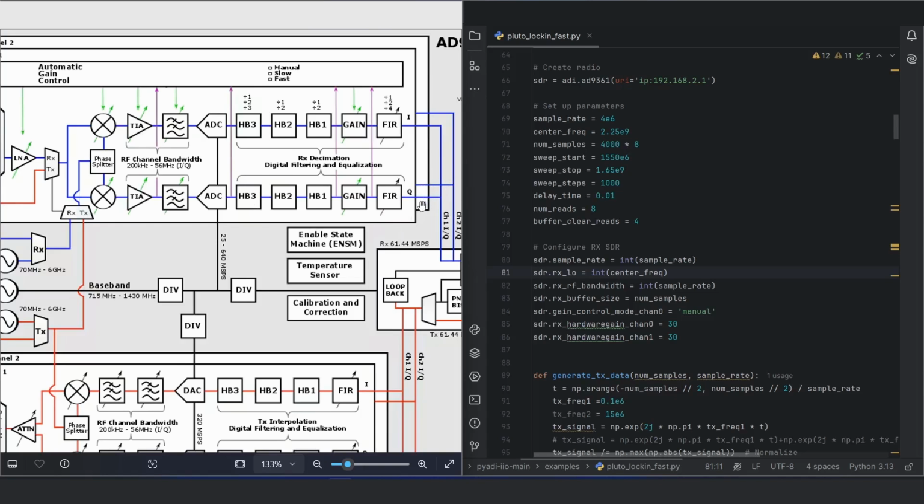In future videos, we will try to see if we can connect to our ADALM-PLUTO using Ethernet to bypass those interfacing speed limitations. But for now, if you are using USB 2, it means that we need to make the output samples of the ADC a speed that is compatible with our interface output.